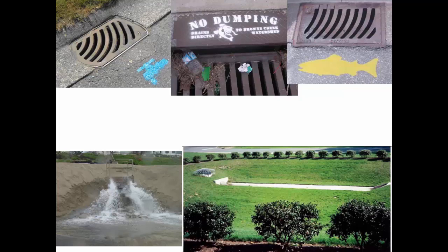A lot of parking lots are very highly impervious, and so there's going to be more runoff from a developed area than there was when it was raw nature and more of the water was infiltrating down into the soil. And so we have to find ways to know the correct size of ponds like this, and also understand how the timing of the water changes when you put in an engineered structure like that.